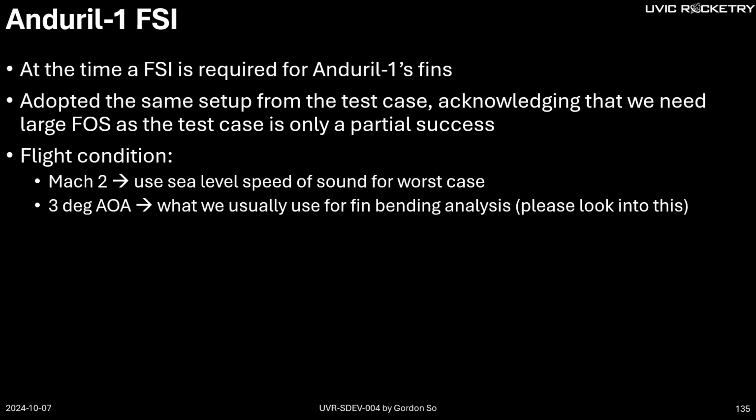That's why I used the NASA test case, because it's basically the same condition we want to know. We want a worst-case scenario, so we do everything at sea level. So even though it's Mach 2, we adjust to the sea level speed of sound to give us the worst case.